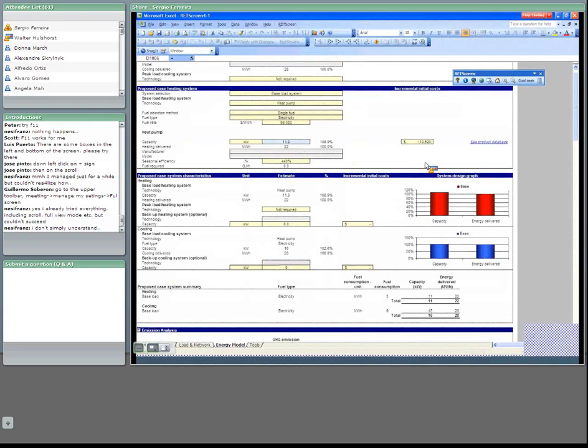Sorry for that. Okay, Walter, but so the COP changes according to the conditions that you have. So a heat pump that your manufacturer says is likely to achieve a COP of 4 or 5 may never reach that in your operating conditions, because your in-house temperature is very different from your environment temperature. Am I correct? Yes, that's correct.